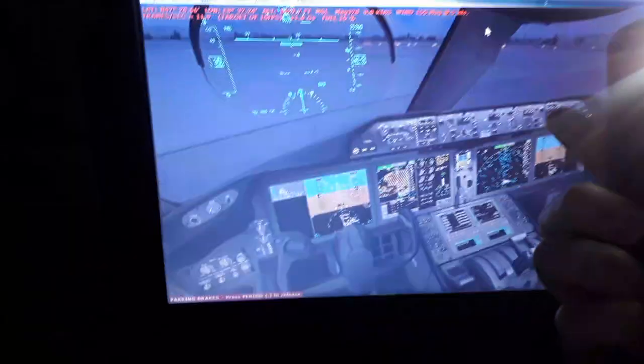Also the FADEC controls as we climb the aircraft higher into higher altitudes, like 20, 30, 40,000 feet above sea level, like 9,000, 10,000, 11,000, 12,000 meters above the sea. As we climb higher, the pressure of the air, the density of the air, and the oxygen level become less than half that of sea level. Also, the aircraft will be flying with an airspeed 2 or 3 times faster than at sea level. So we're going to have a higher intake of air from the front fans. For combustion, the fuel mixture is adjusted automatically from the FADEC. Also, as we descend back to the airport elevation.